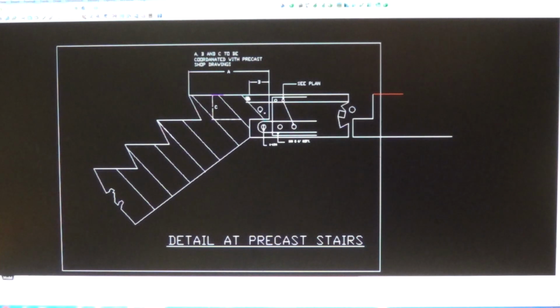And after welding, you can put cement on top of it to erase the gap. You have to cut that precast concrete and provide a steel plate where to weld this reinforcement from the waiting portion of the landing. Alright, that's how they connect this stairs. Alright, that's a simple details for the precast concrete.